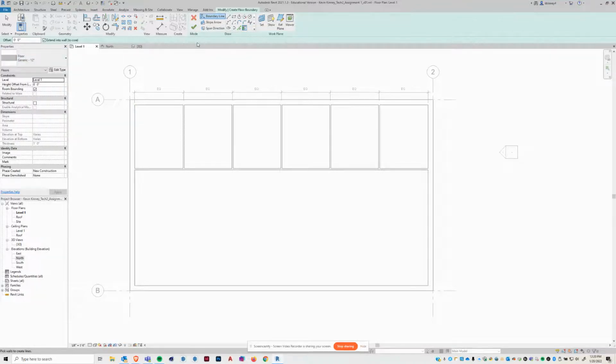Select that one. Now, you'll notice up in the toolbar, it looks a little different. It wants me to draw the boundary of this floor. Whenever you see this red X and green check box here, that means you are currently in a tool. So what Revit is saying is, hey, draw me the boundary for the floor, then hit the green check. So I'm actually going to use the rectangle button to draw the boundary. I could likewise use the line button, that'd be fine.